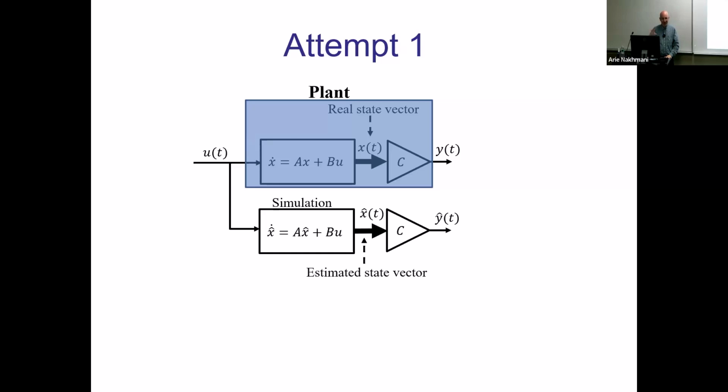So I have a more significant difference here, not only tolerance of how close your real matrix A is to the real system A, okay, to your model. Like, there are differences, so it will be a little bit different. But I'm saying it could be not a little bit different, it could be significantly different. Like the X which is estimated in that system might be completely different. Not even close. And will never converge to the original X.